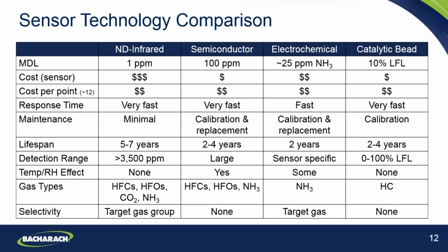So within supermarkets, effective low-level leak detection, and really there we're talking sub 10 parts per million, can be achieved in all refrigerated spaces. So that can include machinery rooms, cold rooms, freezers, display cases, delicatessens, meat preparation areas, bakeries, fish counters, anywhere that is refrigerated within the facility. And it will allow finding small leaks that typical higher part per million leak detection devices simply can't find. It's also possible to integrate the alerts with the refrigerant management software and a building management system.